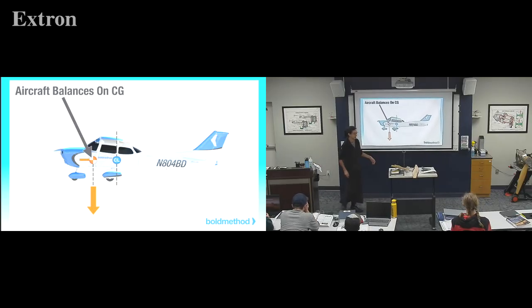Because if we just had those two forces, if I have center of gravity here pulling down, center of lift here pulling up, we're not doing so hot. So what do you think is happening on an airfoil? Yes. So our elevators are actually designed to have a downward force. So air is flowing, giving a downward force on the elevator, so that we have center of gravity, center of lift, downward force, and it all equals out.